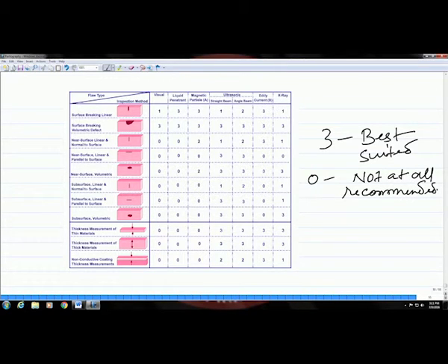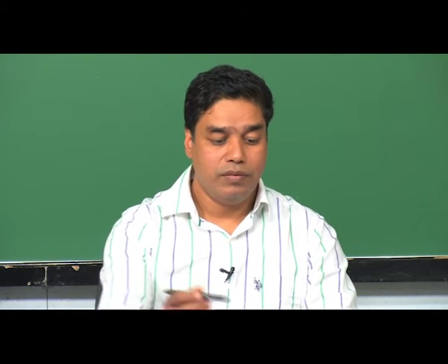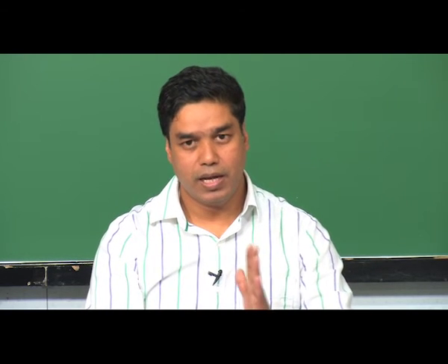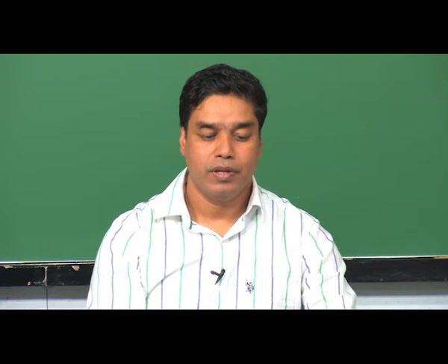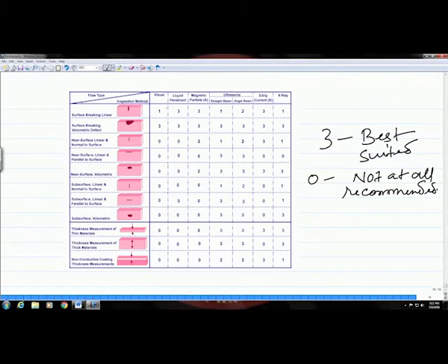Okay, so let us have a look at what kind of defects you have and some examples as to which particular NDT method will be best suited for that. So, if you have a surface breaking linear defect, let us say you have a crack at the surface which is linear. Okay. So, for that kind of surface defect you could see that the visual method is not so good, because the crack may not be big enough to appear to the naked eye, or even with the help of some kind of visual optical aids.